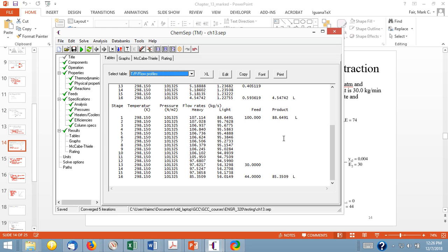Does that make sense for you? So in a two-phase region, that's where they're completely immiscible. They don't mix at all. Right. So this has come to equilibrium now, such that you do have these two streams at either end of a tie line, essentially, within the two-phase region. But the stream coming in, remember, was pure butanol. So in order to reach equilibrium, there has to be some water that goes into that stream to have it reach an equilibrium state.